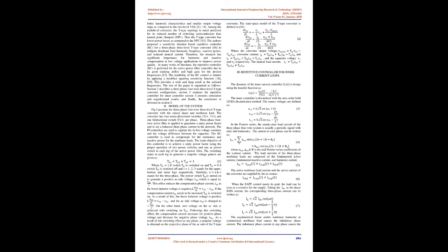The zigzag transformer is a low-cost, high-reliability option to create a low impedance path for zero-sequence current and an open circuit for positive-sequence or negative-sequence current. However, the zigzag transformer may not be a good option for a system with an unbalanced utility voltage. Because its low impedance path for zero-sequence source voltage may aggravate the problem of neutral current and even may burn down the zigzag transformer, the neutral conductor, and the distribution power transformer [11]. Moreover, its neutral line current attenuation level is determined by the source side to zigzag transformer impedance ratio [8, 12].